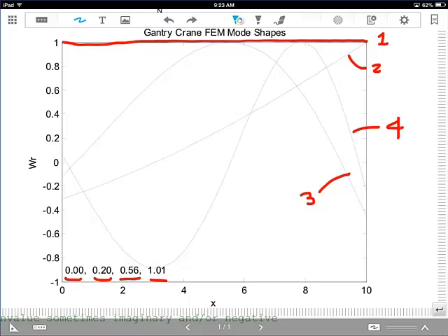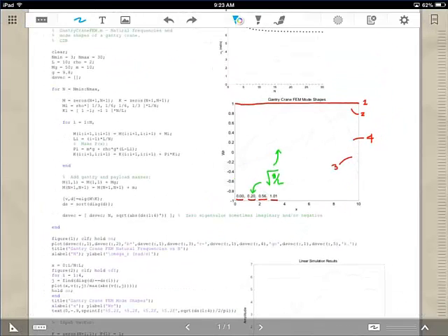And in this problem that's really not a good idea, because the swing mode, the square root of g over L sort of mode, that looks pretty much like a rigid swinging pendulum, is actually very close to, it's only half of the first real vibration mode that has some curvature to it. So depending on what you're doing with this crane, that could be a significant vibration in that second mode.